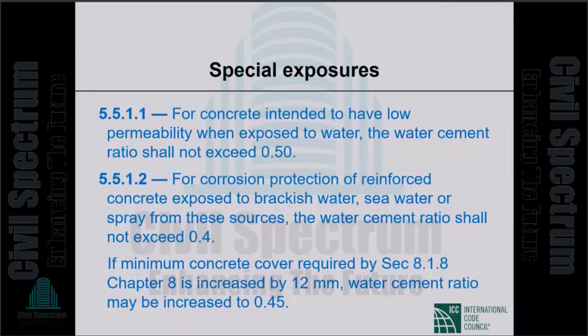Okay. So for concrete intended to have low permeability, so-called watertight concrete, when exposed to water, the water cement ratio shall not exceed 0.5.